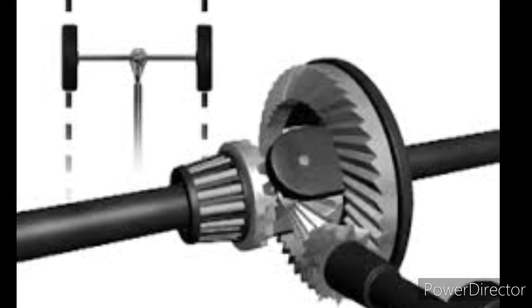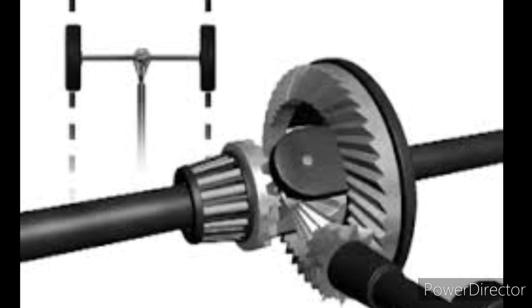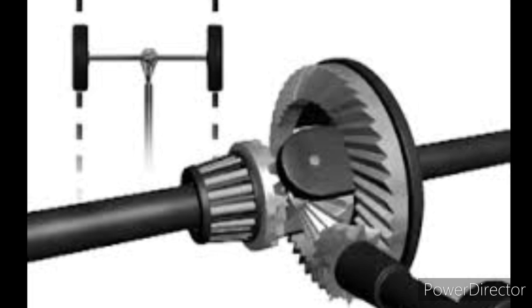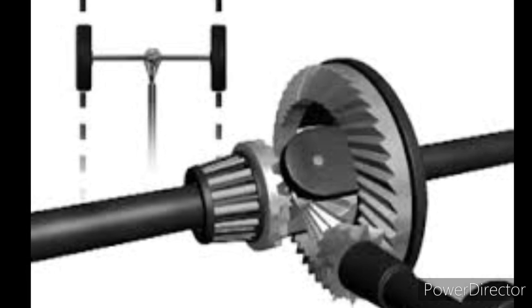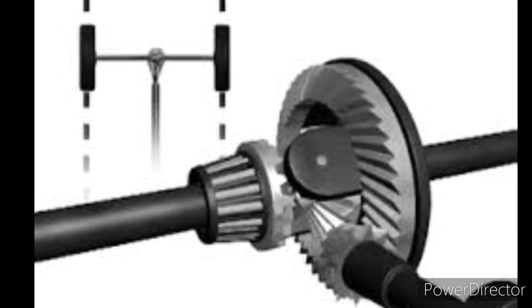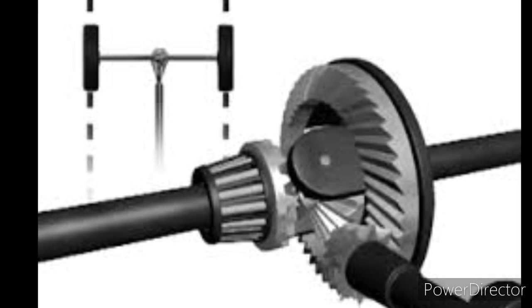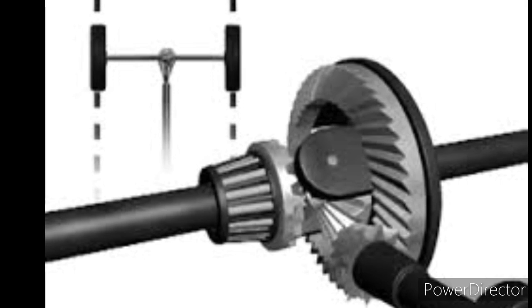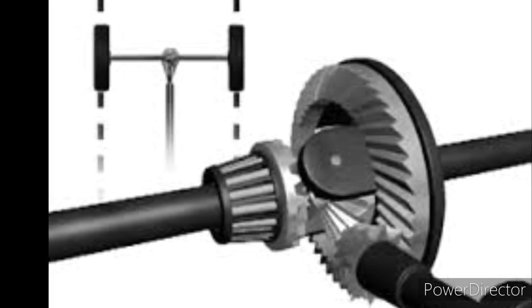If both wheels were on a one-piece axle, the outer wheels would begin slipping as they try to keep up. Slipping is a loss of traction and would cause the truck to skid to the outside of the curve. The differential gears each wheel separately. It drives the inside and outside wheels at different speeds and maintains positive traction to both.